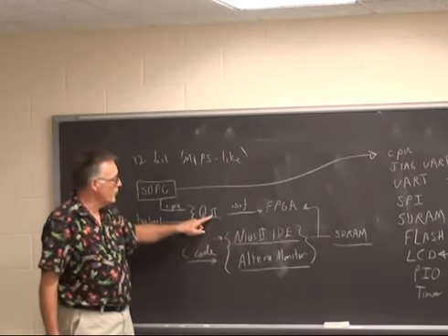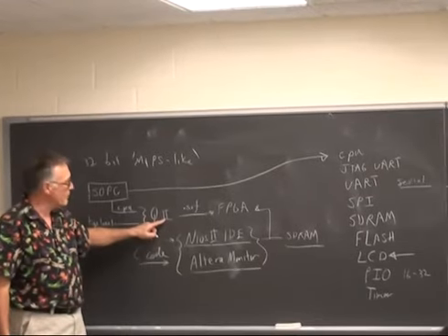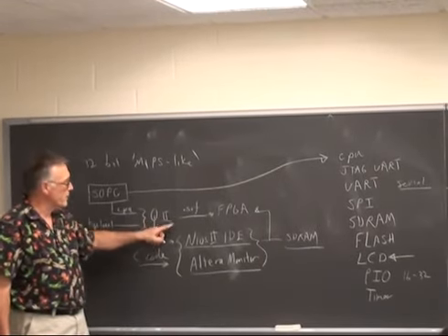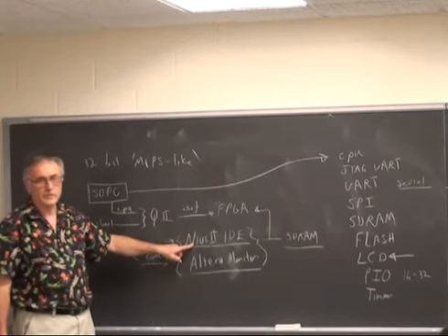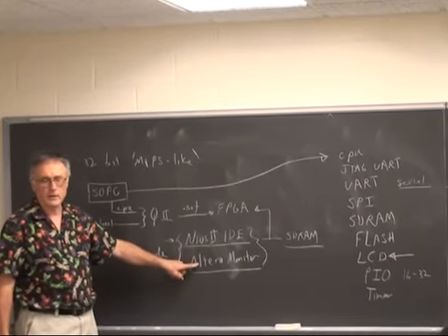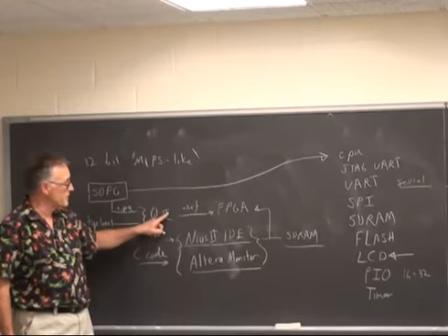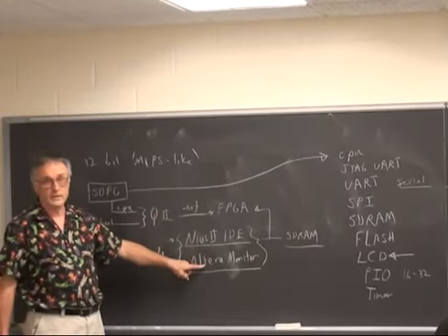If you download onto your laptop Quartus 11.0, you must also get the 11.0 IDE and the 11.0 Altera monitor, and you have to load them in that order. You have to download this first, then this, then this.